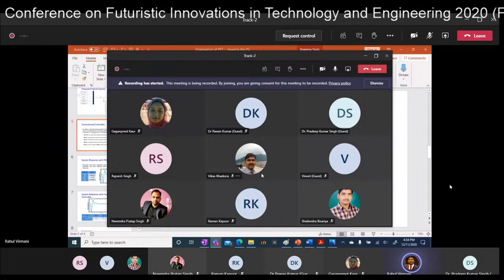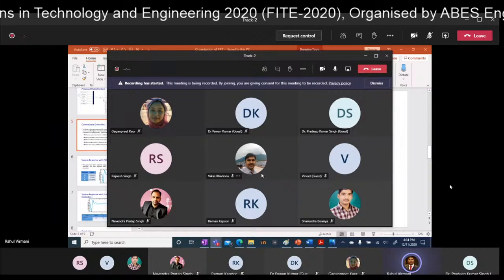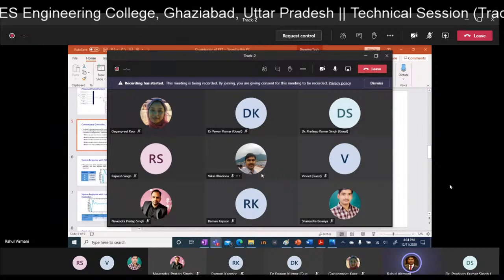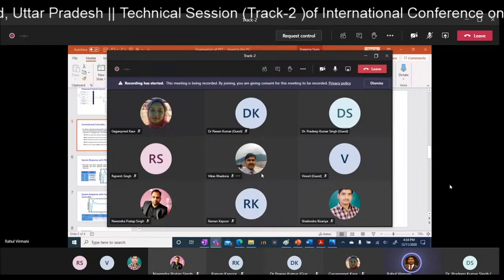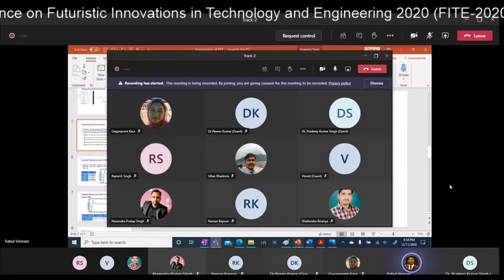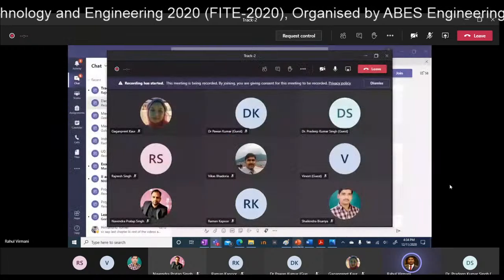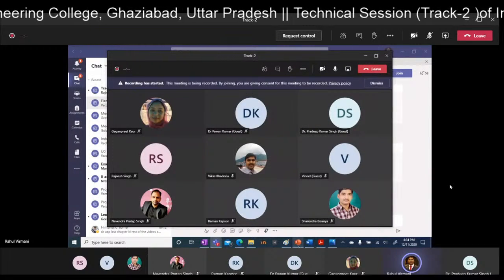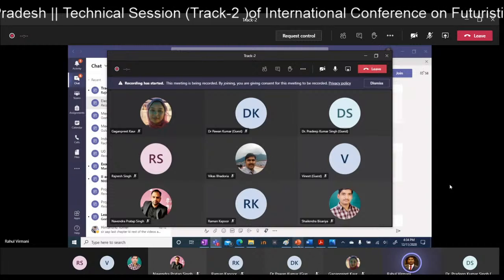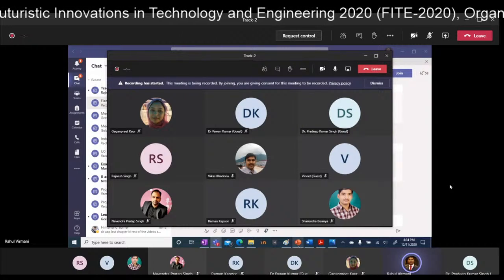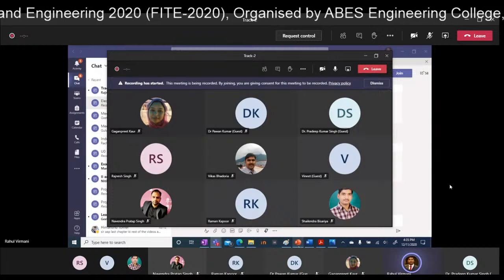Now suppose the temperature is moving, and the heater element is heated so high that the temperature goes beyond 50 degrees Celsius. That's an overshoot. In that case you need to add a derivative control. Now at the settling state, suppose the set point of the temperature is 50 degrees Celsius, but it is settling at 48 or 52. Then at that time you will use an integral control.